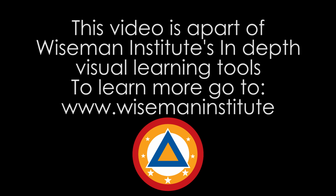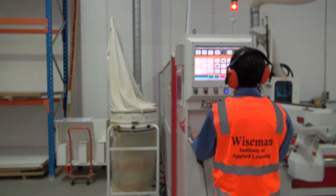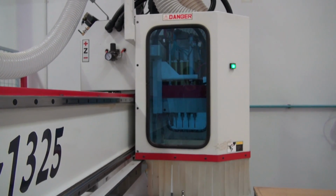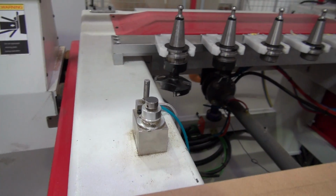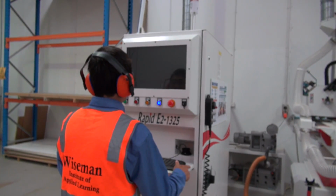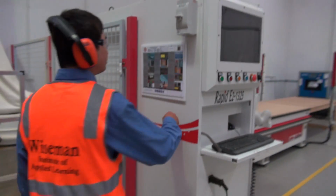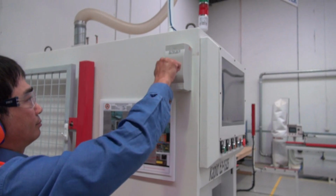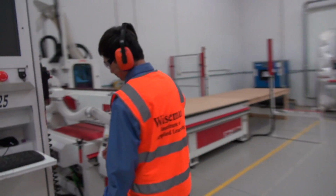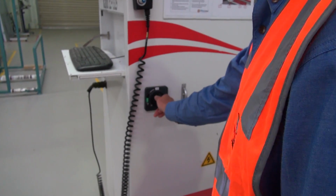The components of the CNC router are made up of many parts. This includes power sources, vacuum and extraction system, locating pin, 3-axis operation, machine tooling, calibration sensor, the offload function, and the most important, machine controller. Main isolated power switch enables power to the machine from the switchboard. If any maintenance is required to be carried out on the machine, the main isolator can be padlocked to prevent any accidental operation. Machine power switch provides power to the machine.